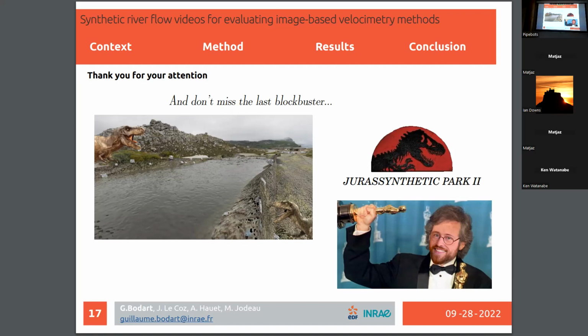Two people in the chat asked a question. Someone asked, were you able to compare the simulated runoff with the measured runoff? And someone also asked, did you manage to compare the turbulence properties? No, with Mantaflow I did not get anything about turbulence properties, so we cannot extract them. This is very basic: you just set an inflow object, an inflow velocity, and then you have your particles and the mesh. And that's it. Then we extract the velocities, but I did not get anything about turbulence, and we did not have any interest in it. And what was the other question?